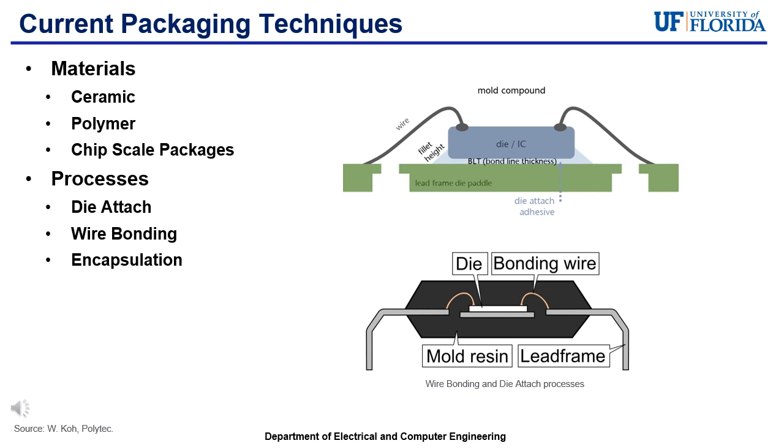In some other cases, an epoxy underfill is then used to fill the gaps around the die to minimize stress of the solder joints. And at the end of the die attach process, everything is then enveloped by an epoxy mold compound encapsulation. The encapsulation protects the integrated circuit from environmental factors and external mechanical damage.